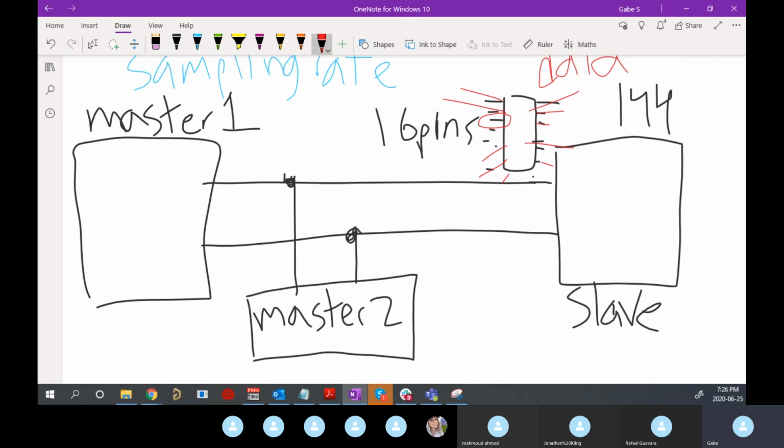In my mind, if you have the pin counts available to you in the space, and you don't have to route your wires physically across long distances because SPI has double the wires, then I like SPI, especially because it's faster and easier to use.